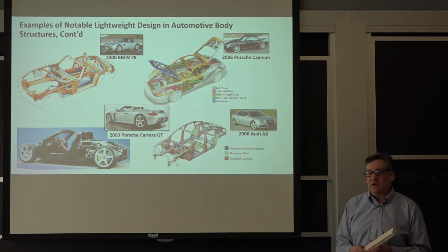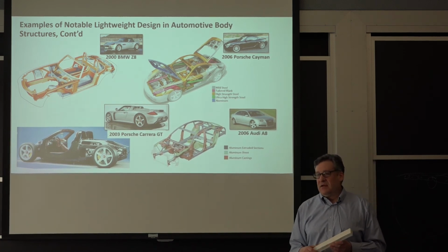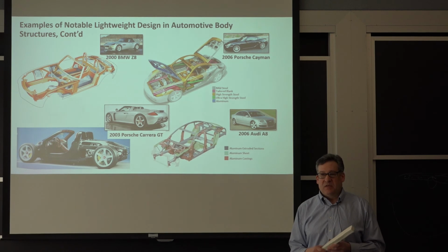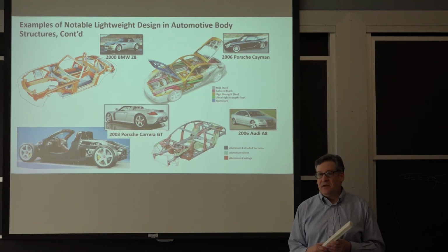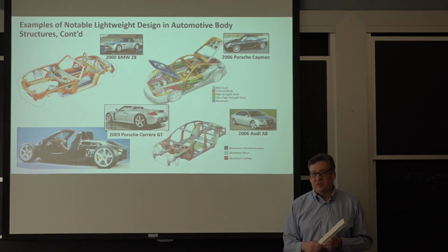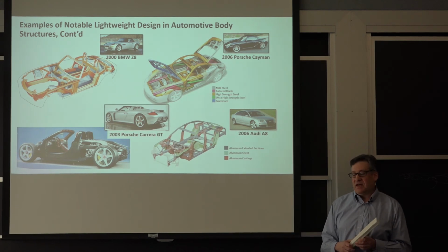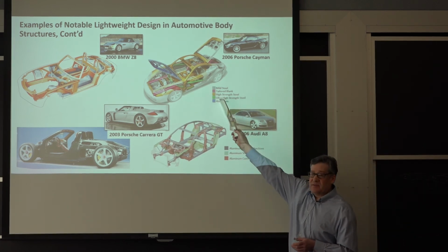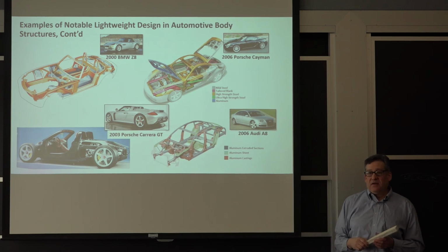If you look at monocoque structures on Formula Ones, they're very much understressed, especially because Formula One has weight limits. But the torsional stiffness, I have a friend who used to work at McLaren, so I know this. The torsional stiffness of a McLaren carbon fiber tub, for example, is about 60,000 Newton meters per degree. The best cars on the road, like this Porsche Cayman, is about 40,000 Newton meters per degree. Your average Toyota Camry, that kind of car, is probably around 20,000 Newton meters per degree.